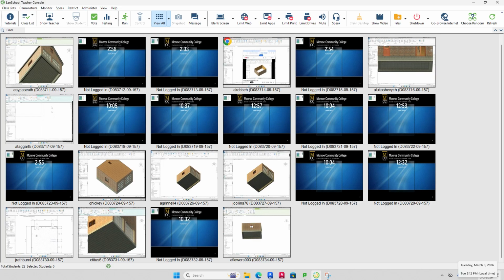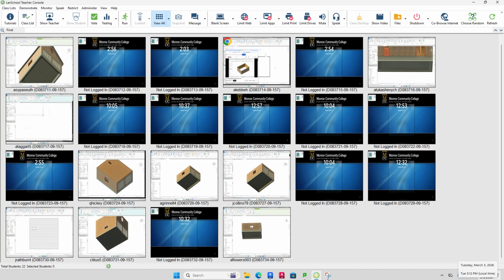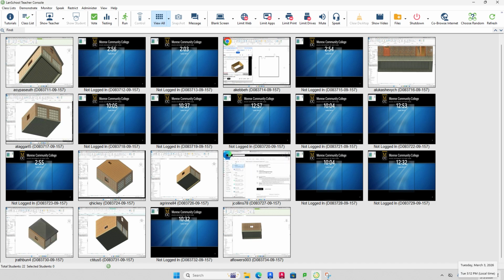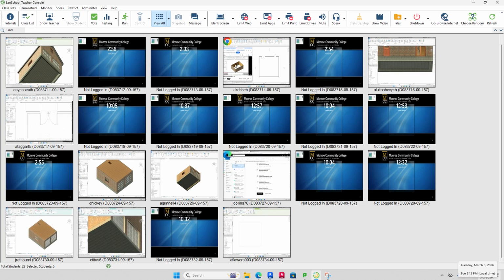Once you're done making the floor, you hit the green check mark to accept it. Put the slab in. You go to structure, and then you go to slab edge, and then you just click on the edges as you go around. And you grab all the sides right there.